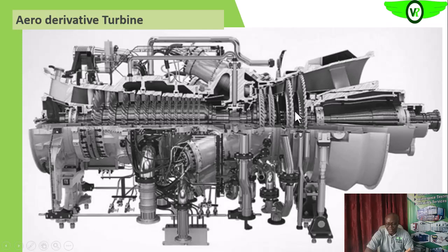And then this is the power turbine that will generate the rotating mechanical energy that we need for our load, either to drive other mechanical equipment, generators, compressors, or pumps. So this shaft is coupled to your load or to your gearbox before your load. This is the power turbine. It does not have any connection here, so they are aerodynamically coupled, so to say.